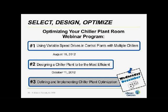Question is, what is PSID? That's pounds per square inch differential. Pounds per square inch is nothing more than like kPa or bar differential. So it could be kPaD, it could be bar D, or PSID. It's just the units in IP. But it's a rating for static, dynamic, and close-off pressure differential you can put across the valve and still have it work properly.